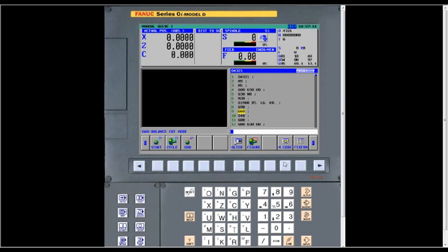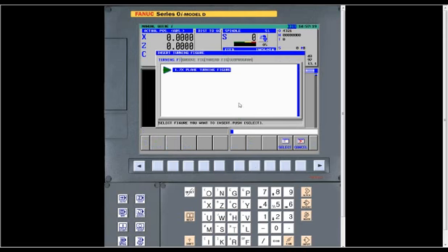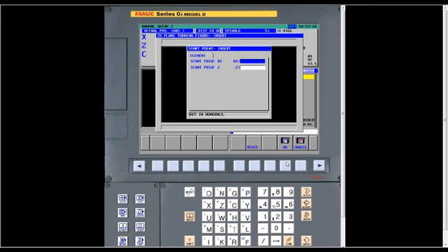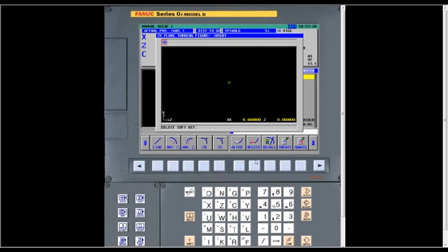Well, that's where, when you go in to do a turning figure, Mark, you can go in and draw it. Once you select that, it takes you into a screen where you define the start point. I'm sort of showing it here. Then you have lines, arcs clockwise, arcs counterclockwise, and corner radiuses.